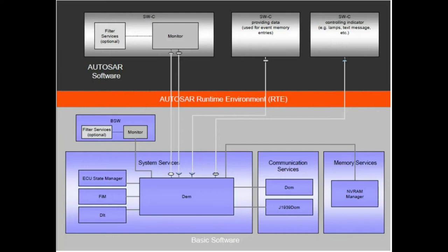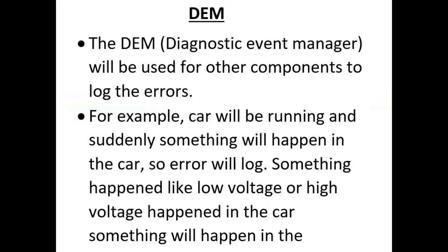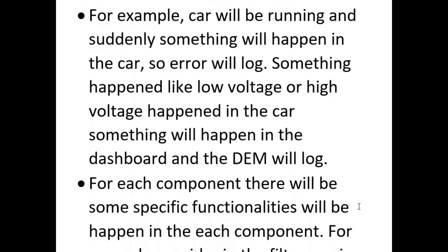Then what is DEM? I already mentioned that DEM is the Diagnostic Event Manager, used by other components to log errors. For example, the car is running and suddenly something happens in the car, so the error will be logged. Something happened like low voltage or high voltage, or something happened in the dashboard, and the DEM will log it. For each component there will be some specific functionalities.